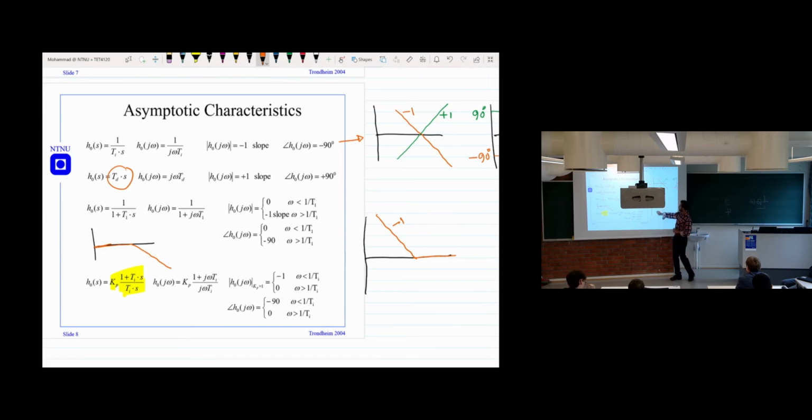So what does this mean, a PI? If we have an input DC component, then you have a very large magnitude. This means it can amplify it. But if anything has a higher frequency, then it can suppress it. So that's what we see here. And here, it should not be 0. When it's omega, then it would be Kp at this point. It's the Kp in decibel.